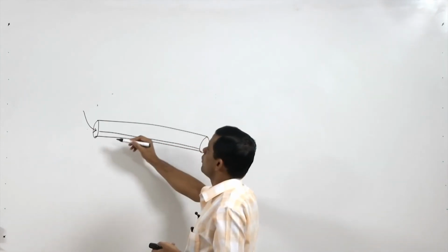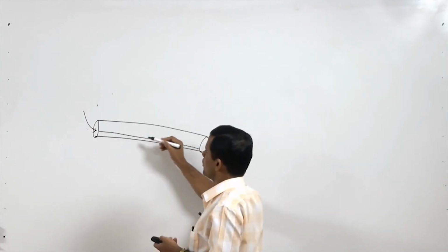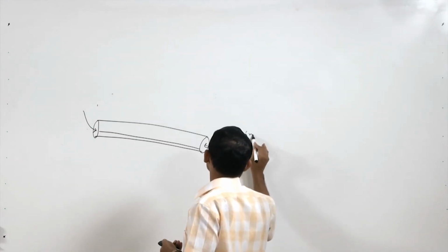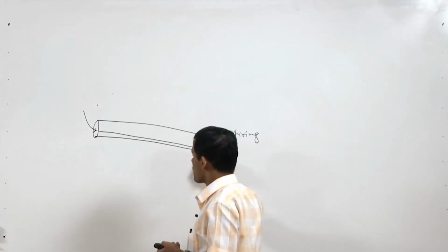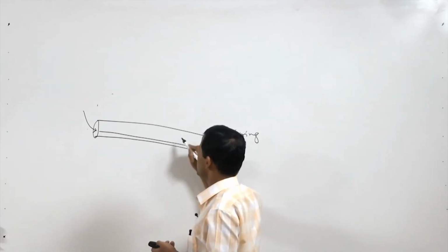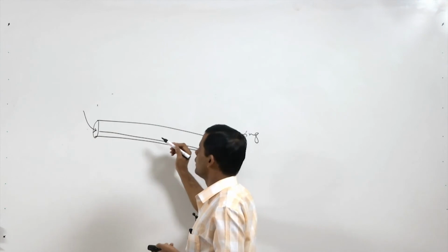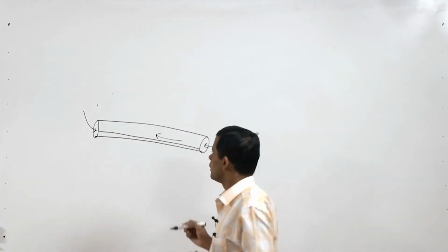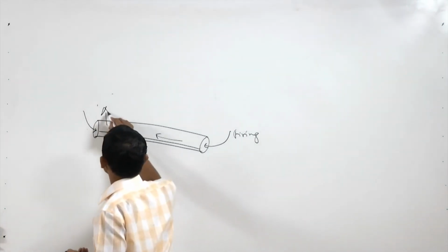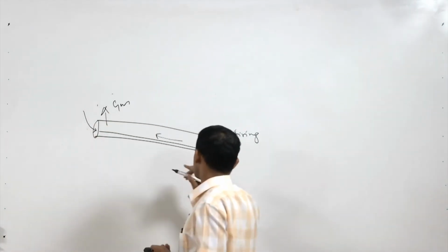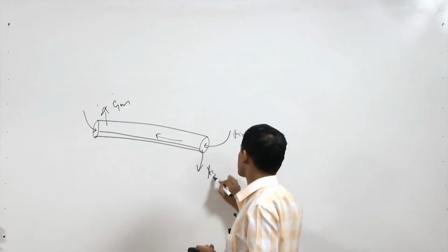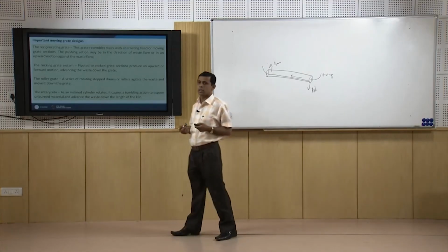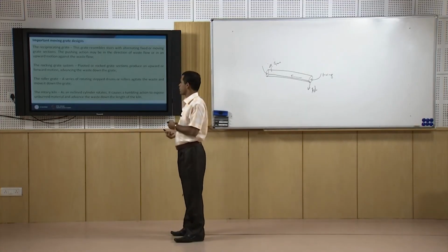So, the material will move downward and from the other end we will give firing. Once initial firing is there, high temperature is going on, so combustion takes place, and gradually the combustion goes on. So, gas will go upward and escape from this. From this we will get gas and from here we will get ash. So, this is rotary kiln, and rotary kiln has wide applications for solid waste incineration.